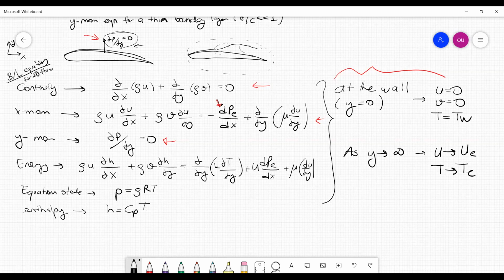The solutions will tell me, for example, how the boundary layer grows on top of that solid object: the delta variation, delta star variation, theta variation, the displacement thickness and momentum thickness variations along the body. Plus, I can get the velocity field, or the velocity variation function, within the boundary layer.